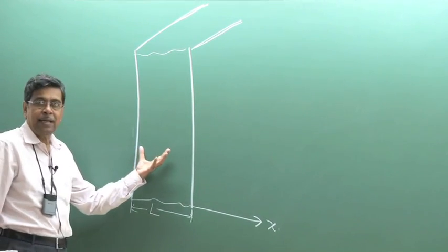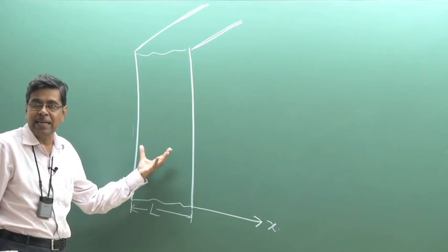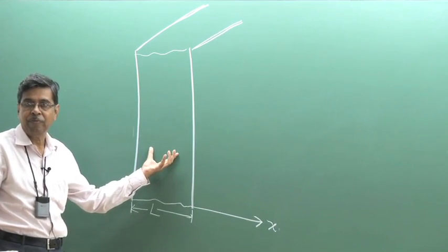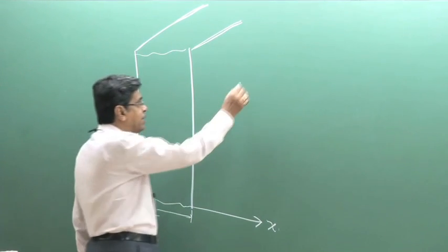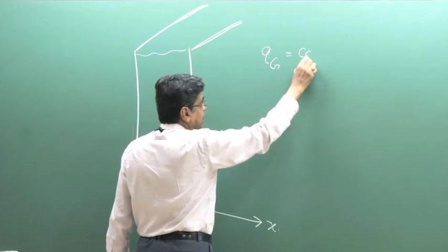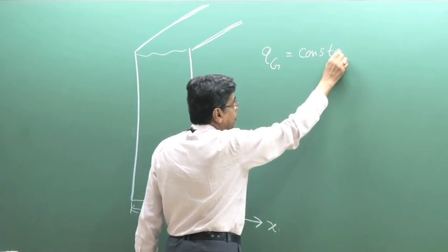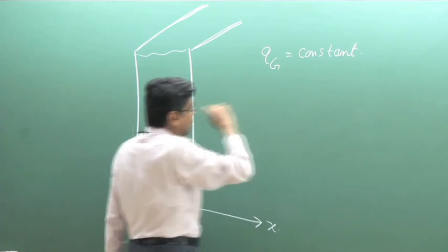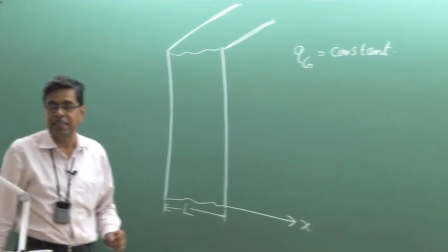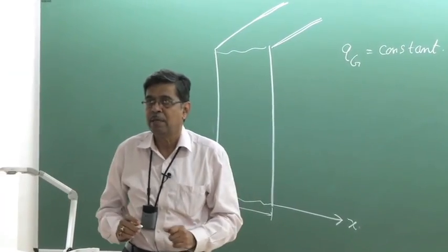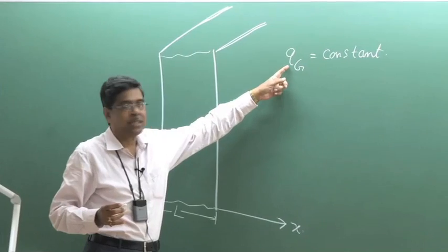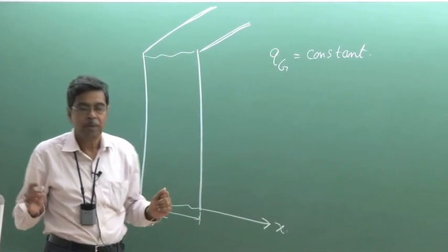There is heat generation, or thermal energy generation, within this wall, this solid material. The volumetric heat generation qg is constant, that means a uniform rate of thermal energy generation per unit volume. Point to point, the thermal energy generation per unit volume is constant. So the total thermal energy generated can be expressed as qg times the total volume.